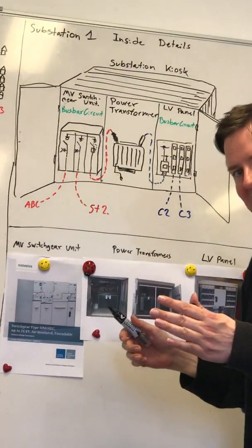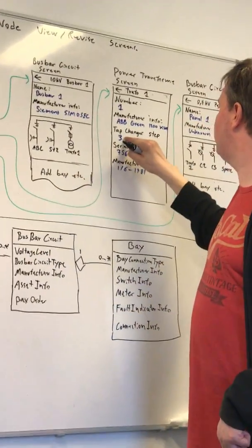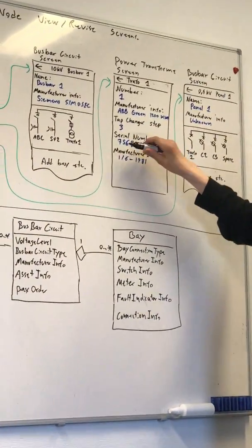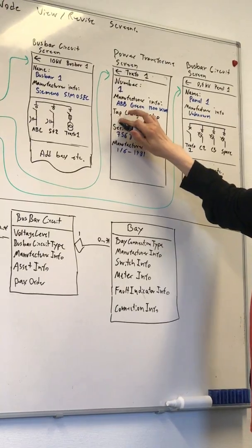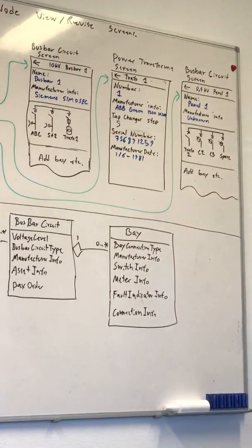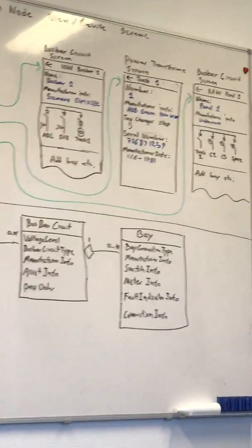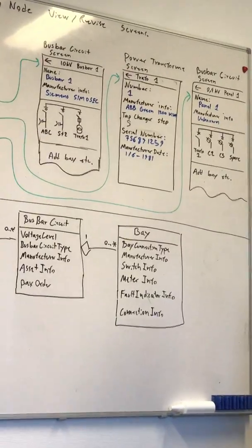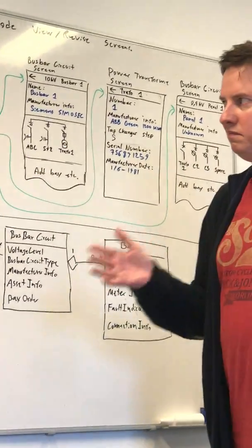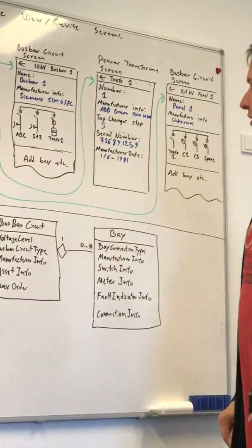Normally it is in neutral, but if the voltage to the consumer is too low, for example, they can put it up. Then they will put this one to step 3, maybe they put it to step 5. Actually, the tap changer step is the step that you can adjust how many volts in the power transformer. Okay. This is something that if they play with that, or if they change that, that's some information we like to have in the system.